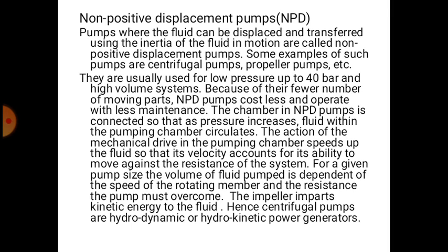For a given pump size, the volume of the fluid pumped is dependent on the speed of the rotating member and the resistance the pump must overcome. The impeller imparts kinetic energy to the fluid. Hence, centrifugal pumps are hydrodynamic or hydrokinetic power generators.